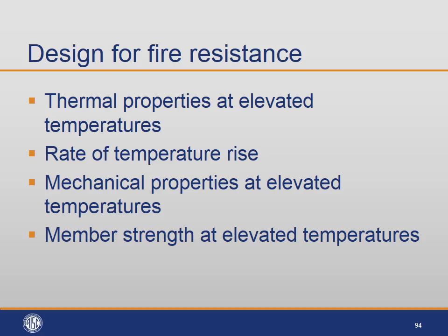So firstly, what do you need to know in order to calculate the fire resistance of a structural member? Well, you need to understand the thermal properties at high temperatures, which will help you calculate the rate of temperature rise, because you'll need to know what the column will be doing after 15 minutes, 30 minutes, etc., exposure to a fire. And then you need to use the mechanical properties in order to calculate the strength of the member at elevated temperatures.